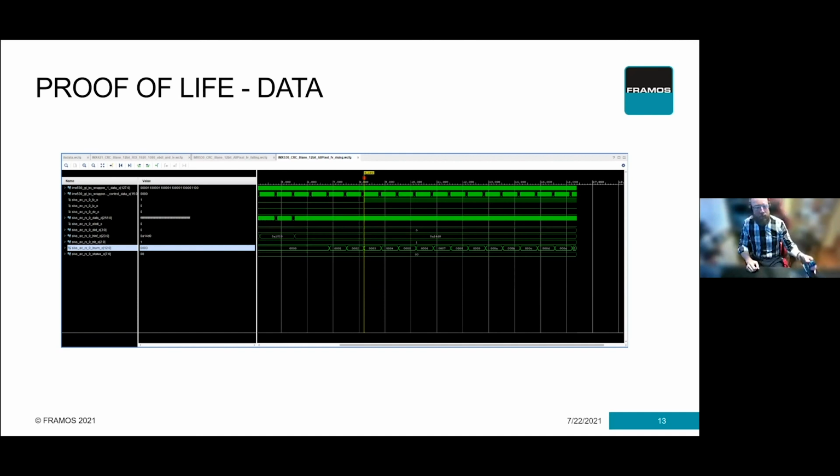Other things to say: try to do it with your complete optical setup. Lenses have color to them. They also add shading in, and the shading also affects any kind of denoising that you'd have in your ISP. So test that final system as early as possible.